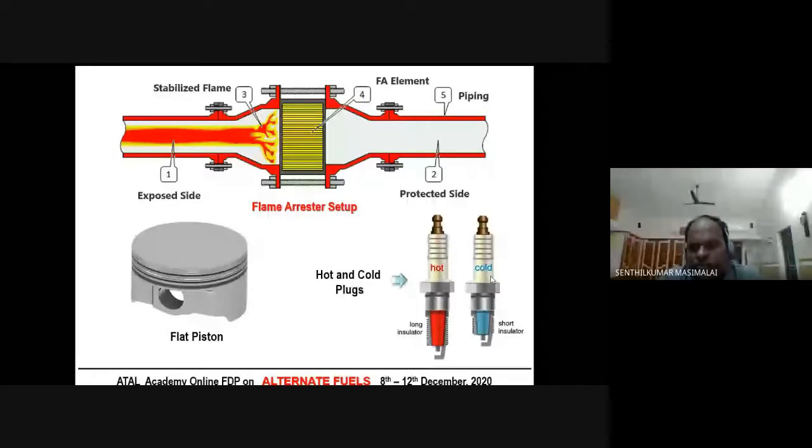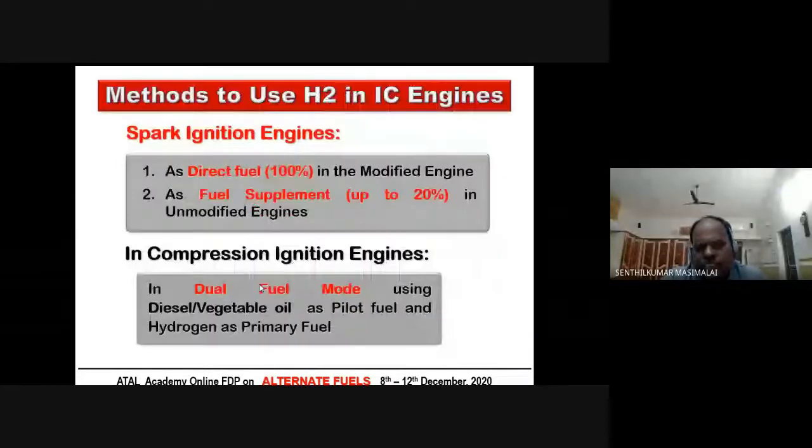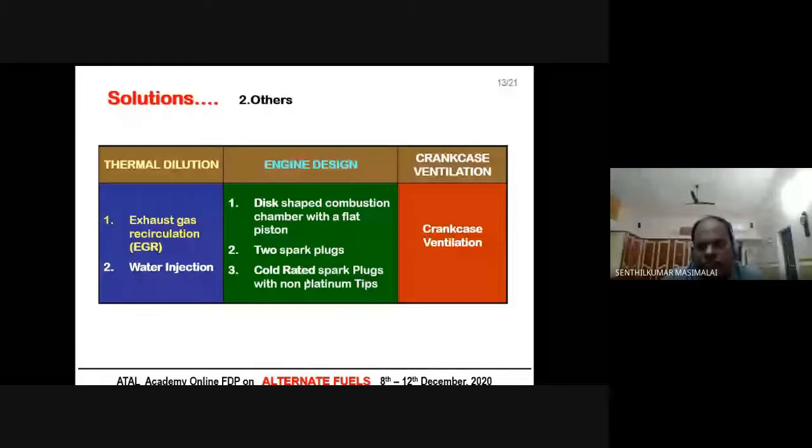And also cold rated with non-platinum tip. Generally platinum will be placed here in our spark plug. This platinum should not be there in our hydrogen fueled engine, because the platinum will react with the hydrogen and it will have some other effects. So to avoid that, non-platinum spark plugs with the cold rating are important. So this is about the engine design.